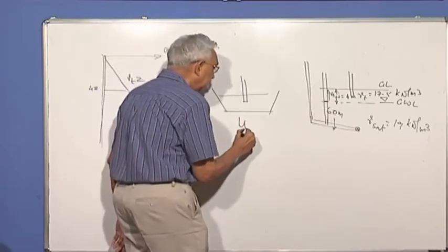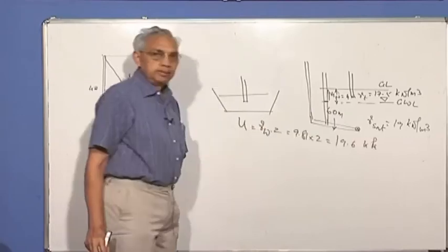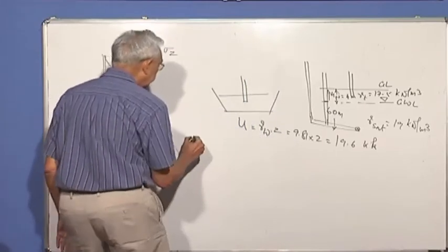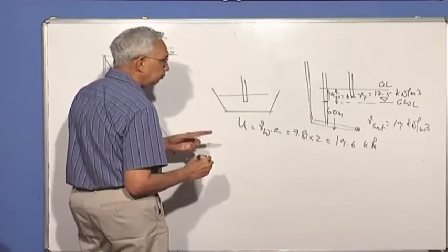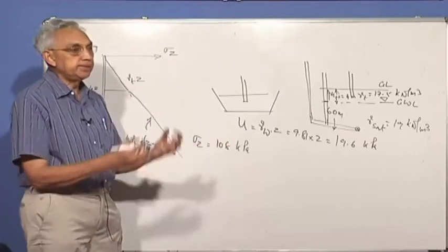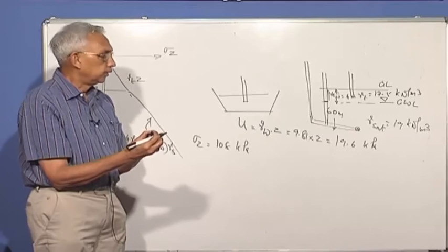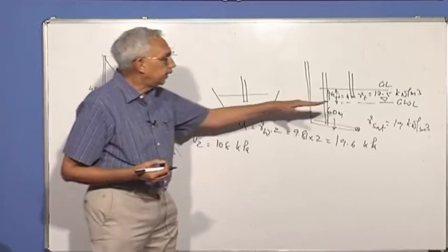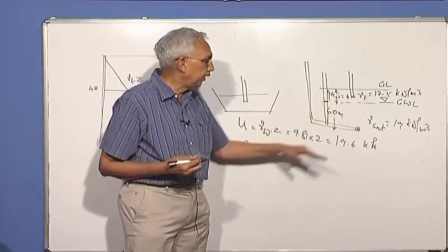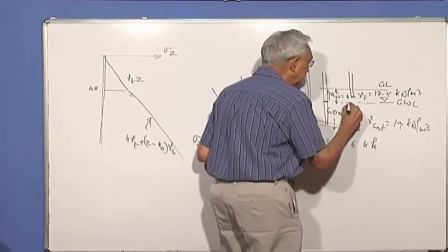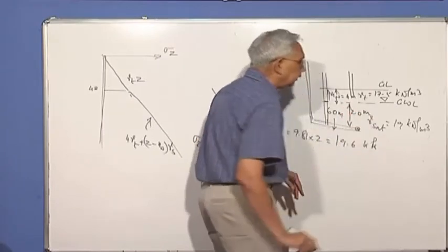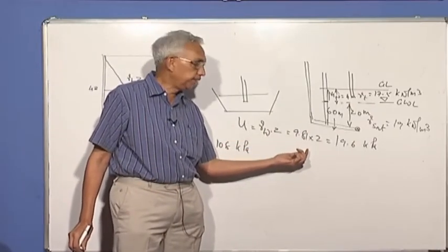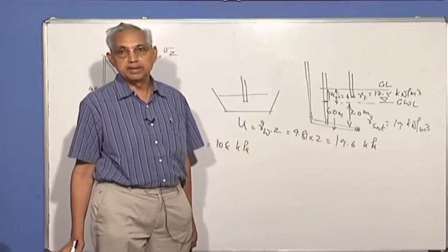So can I say the pore pressure will be equal to, so what you have found out is the total stress here at 6 meters, sigma Z is equal to 70 plus 38, that is 108. That is the total downward force. But in the pore water, the pressure corresponds to the depth from the top of the groundwater level to the point. So this distance is 2 meters. Corresponding to 2 meters, unit weight of water is 9.81 kilonewton per meter cube, so the pressure will be equal to 19.6.